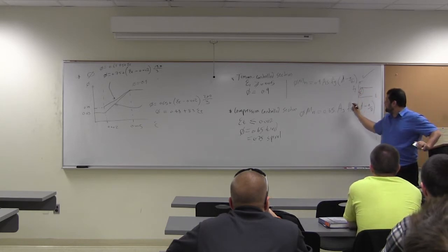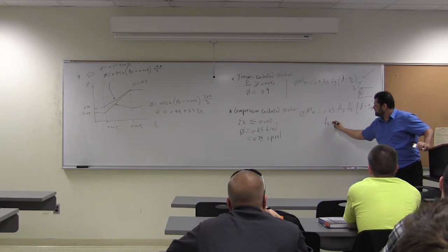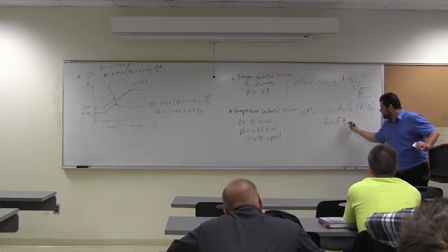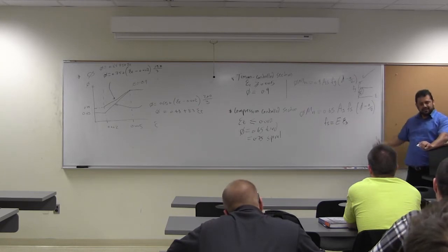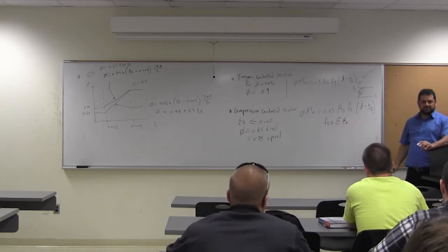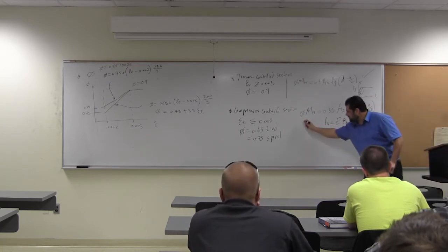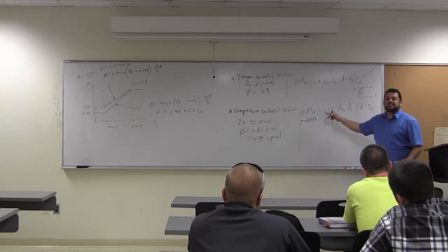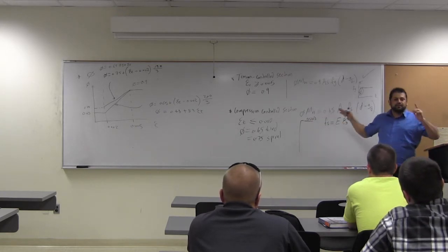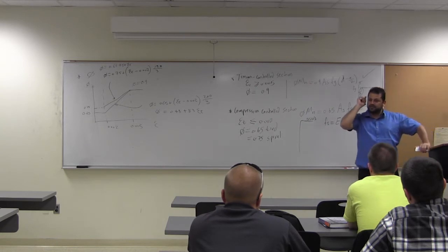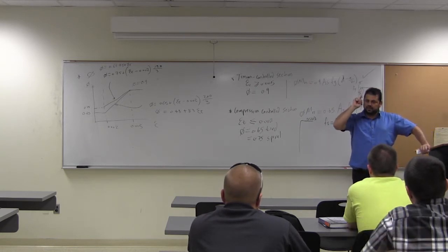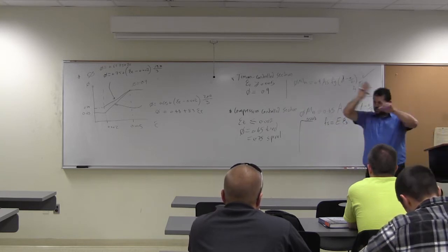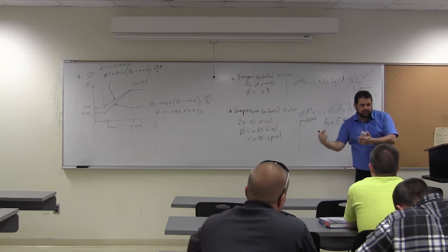It means Fs equals what, guys? Hooke's law. E times epsilon s, E times the strain. So where do you get epsilon s from? From the strain distribution. This number is still fixed. Beams will fail when the compression strain in the concrete reaches 0.003. Fixed point for analysis.